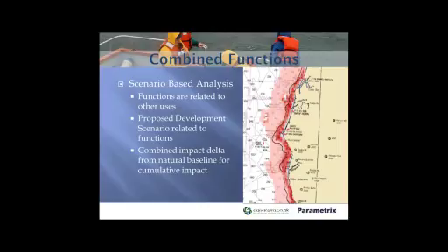In the tool, we're using a scenario-based analysis, and so functions are related to uses, and proposed developments then are run through a series of ArcGIS model builder tools that tie to an MS Access database that captures those impact assumptions. The important thing, and the reason I mentioned the model builder and the Access database, is that they're flexible and they can be changed as new information comes in. Different scenarios can be understood, or even sensitivity analysis across different scenarios and different ranges.